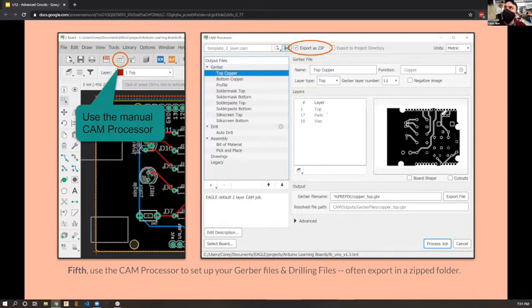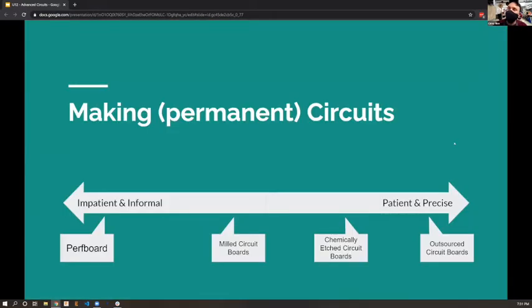So you can choose the top, the pads are all the places where you'd solder to, the vias are through holes. You can see sort of the ground plane connections like this show up and they give some extra detail, but you process that job. And once you've got a design, now we can talk about how do you make things.